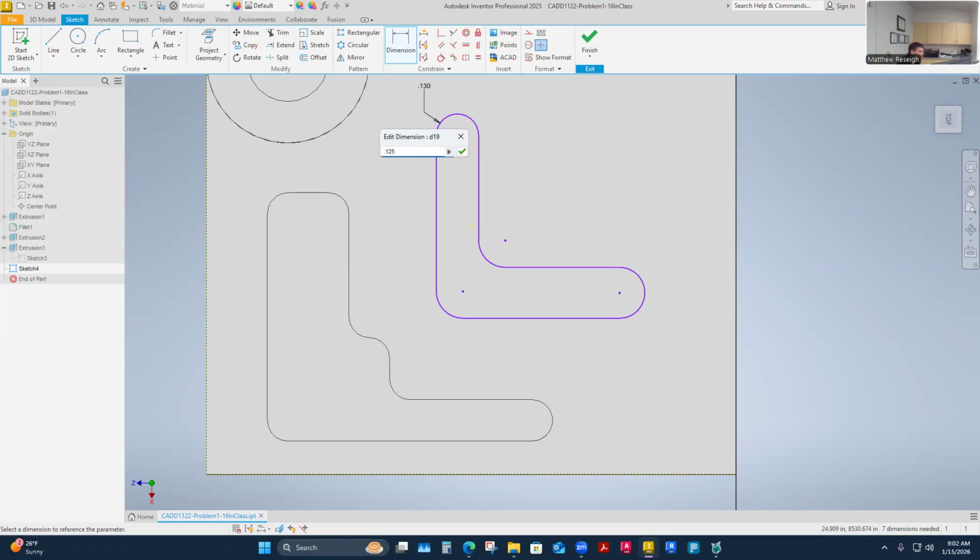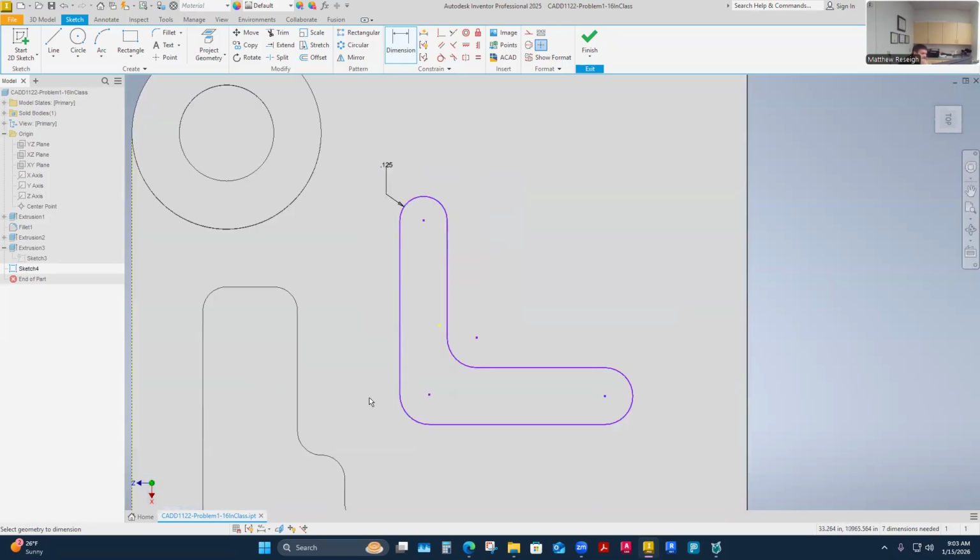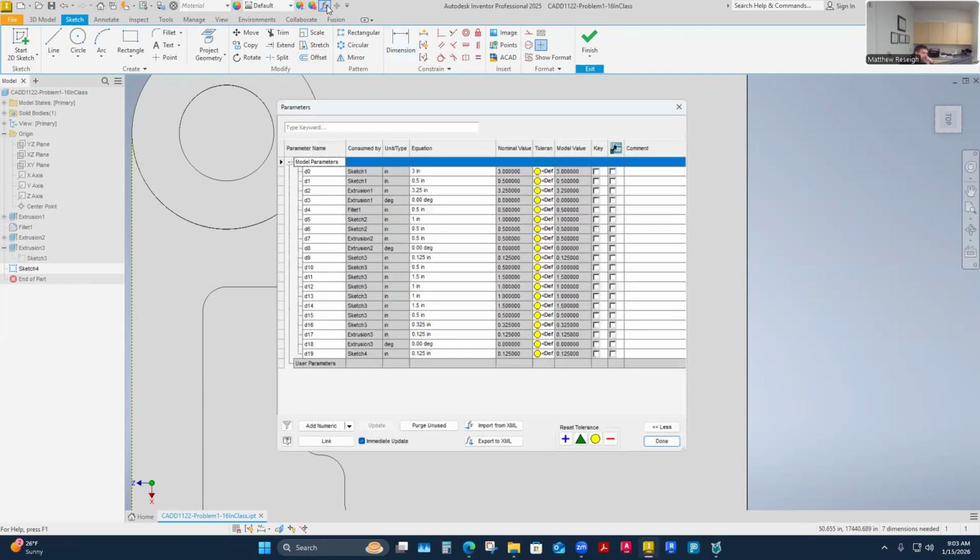I'll always show you what I'm thinking in my mind. I haven't looked ahead at what the other sketch is and what its fillets are, but if all the fillets on these embossings were 1/8 of an inch, then I might want them all to be driven by the one dimension on this first sketch, which, if I remember showing you up on your quick access toolbar, you have an f of x up here.